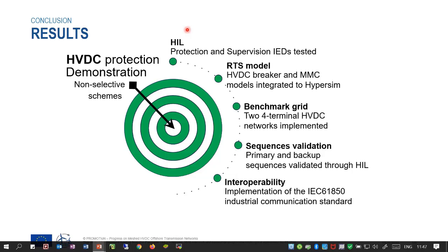Use of IEC 61850 as communication protocol for this test showed that 2 different pieces of hardware were able to exchange comprehensive data for the application of protection and supervision. Supervised control and protection was successfully designed, implemented, and tested, including startup and restoration.